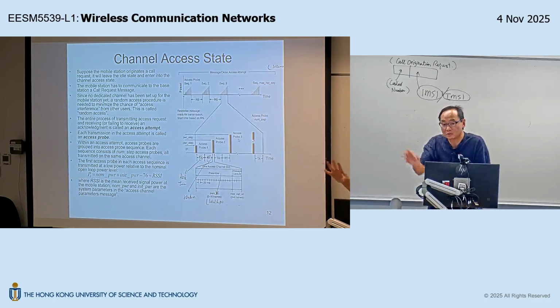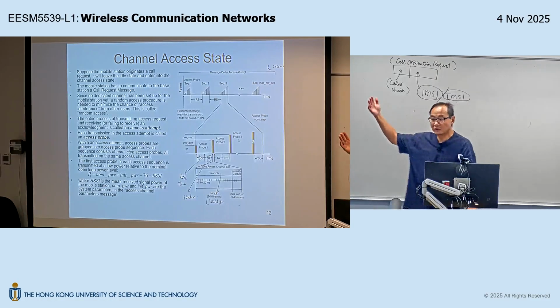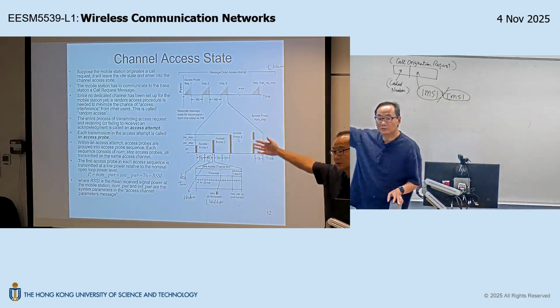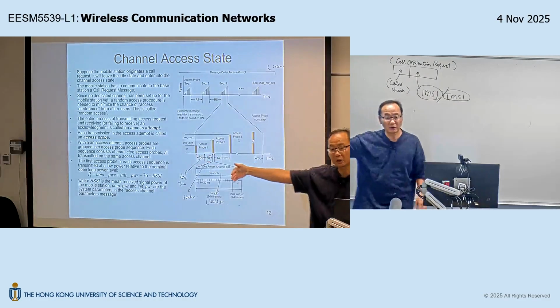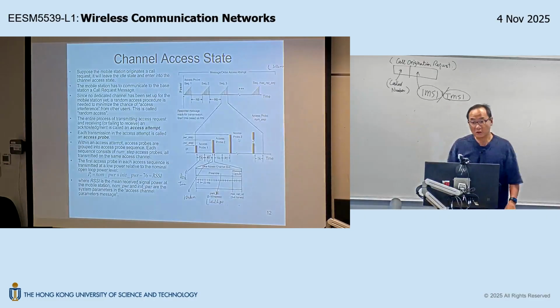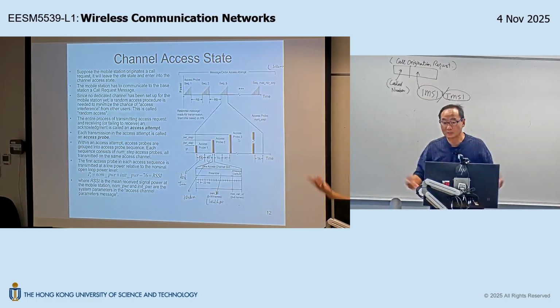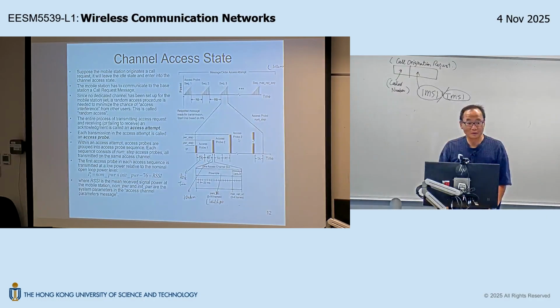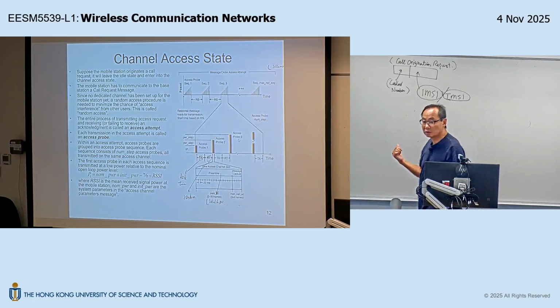Well, imagine in this classroom, if we practice transmitting the random access in maximum power. On average, if there's some observer observing the classroom behavior, that person will hear the classroom being very noisy, right? Because everybody is shouting. And remember, this is uplink. Uplink is operating using random CDMA. And remember, what's the capacity limit for random CDMA?